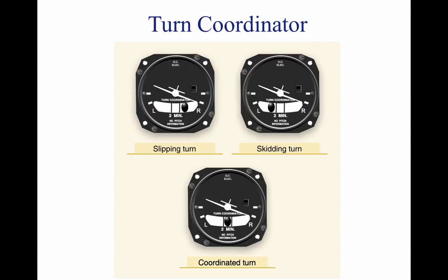The inclinometer is used to depict aircraft yaw, which is the side-to-side movement of the aircraft's nose. During coordinated straight and level flight, the force of gravity causes the ball to rest in the lowest part of the tube, centered between the reference lines. Coordinated flight is maintained by keeping the ball centered. If the ball is not centered, it can be centered by using the rudder. To center the ball, apply rudder pressure on the side to which the ball is deflected. Use the simple rule, step on the ball, to remember which rudder pedal to press.